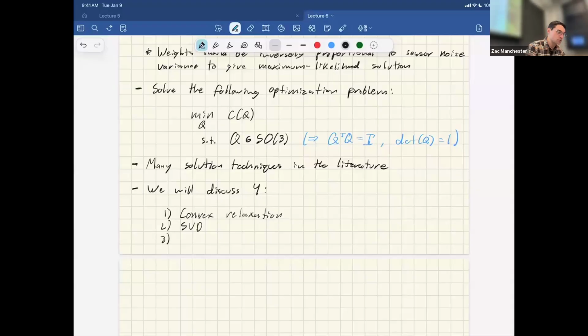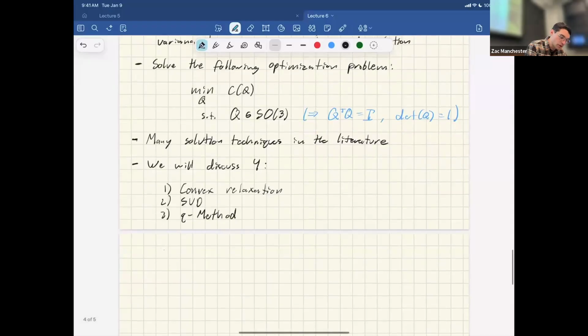The third one is maybe the most widely deployed in practice on spacecraft, called the Q method or the Davenport Q method, which is a reformulation of this problem in terms of quaternions instead of rotation matrices. And the last one, which I think is the cleanest bridge to Kalman filter land, the next topic after this, is to use Newton's method to solve this thing kind of directly.